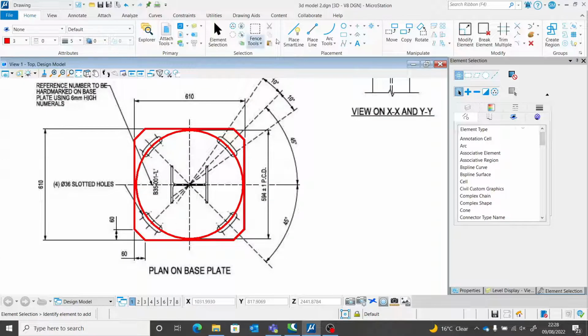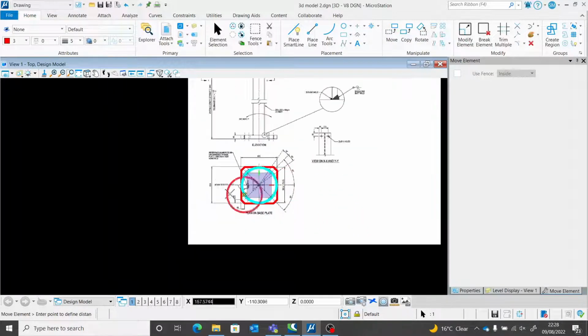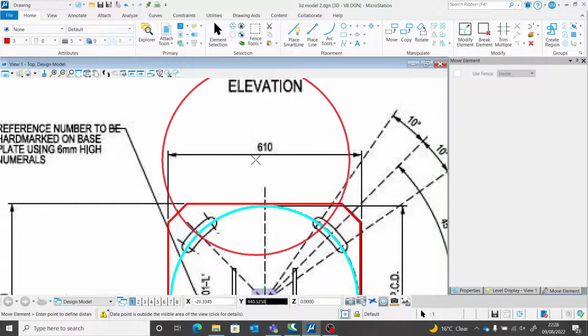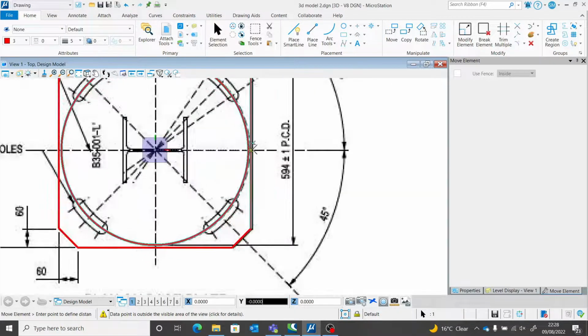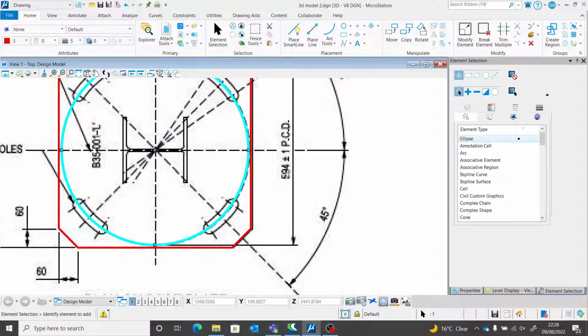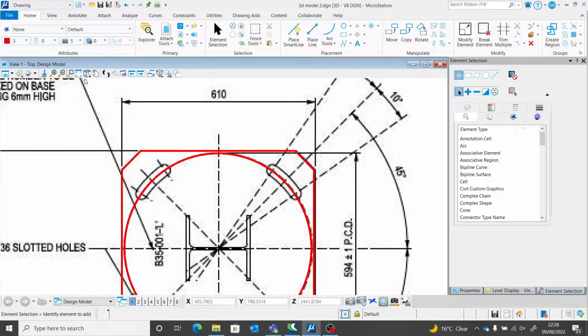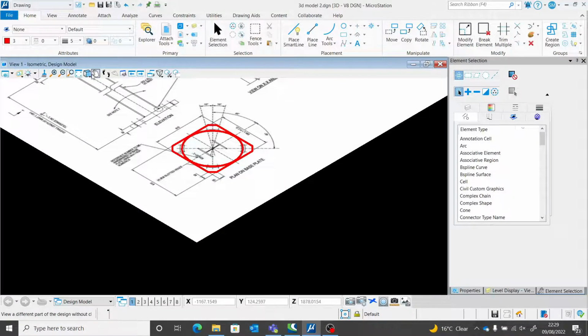I think that's the middle, but what you can do to make it center is move it. So I'll move it by the center, then you can use enter. So move it to the middle, it should snap here. Then you should move it up and down again. Enter. So try to use that, and now that is center. Okay, good. Because we're working in 3D, always do isometric to check. So it is fine, they're all in the same plane, we're good.